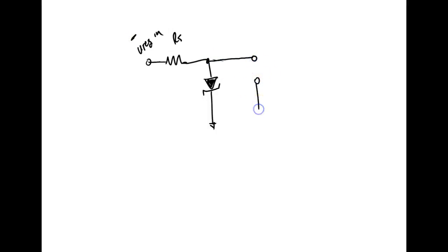Number 3, design and draw a Zener regulated power supply using the following parameters. We got unregulated voltage, we got a negative voltage, so this is a negative regulator. So what my zener will look like is, here's unregulated Vin. Here's my RS. Here's my zener. Because this is negative, we have to put the zener in there reverse biased, right? And this is going to be my load. V out is going to be minus 22 volts.